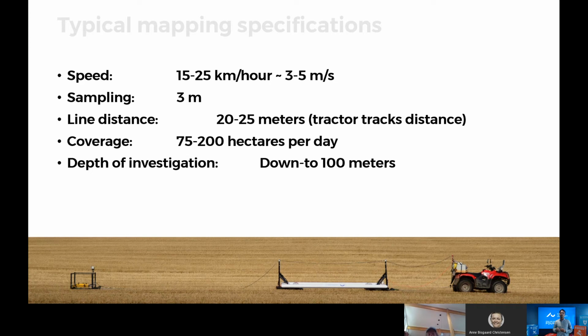But 3 meters is way too many soundings if you're running the whole day. So we downsample them, honestly, to 10 meters. That's what we can probably resolve with the system. If you're running a farm field, you can go back and forth, so you can have a line spacing between 20-25 meters. So you can cover the whole area and create the 3D images afterwards.